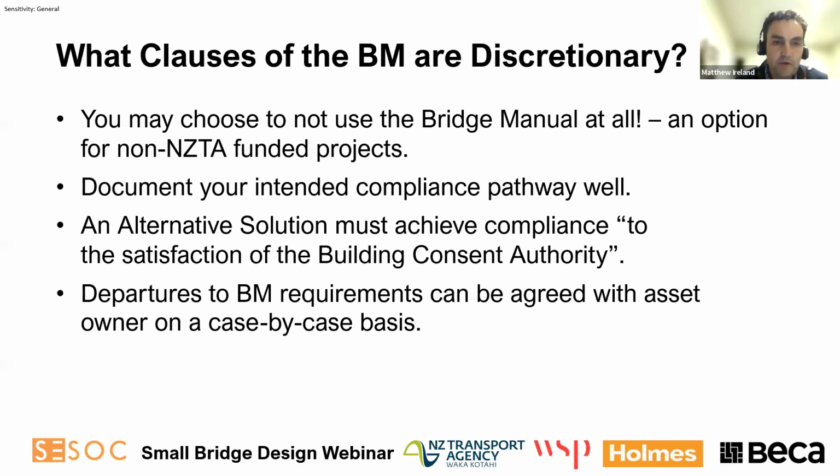Most importantly, you need to document your intended compliance pathway well, so that any reviewers can understand what you based your design on, and also the Building Consent Authority. The key thing there is that any alternative solution must achieve compliance to the satisfaction of the Building Consent Authority. At the end of the day, they're going to be the one making the call there.